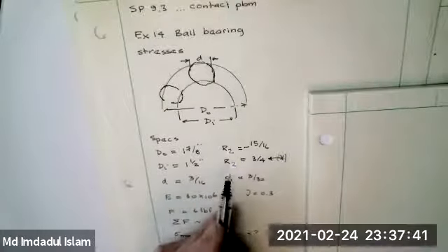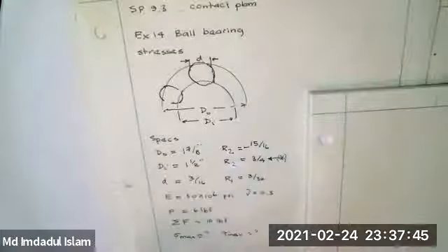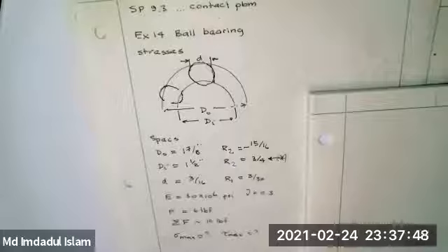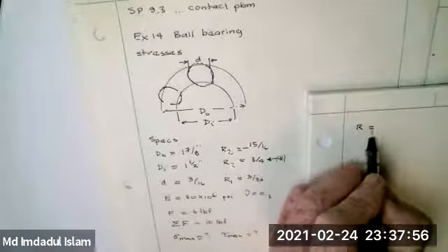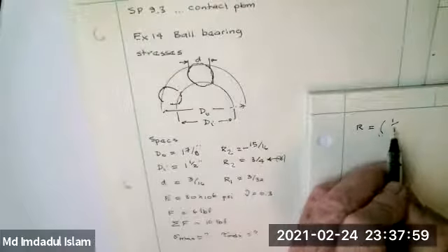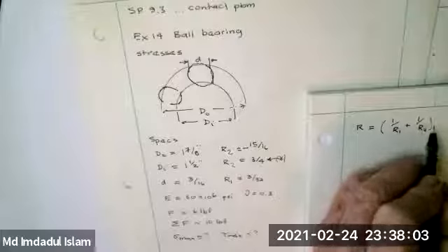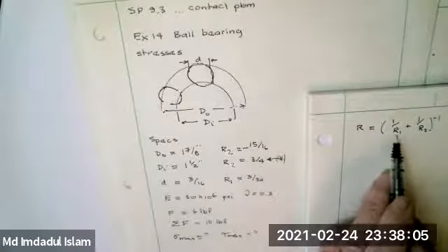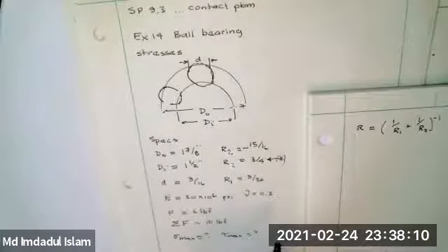As I said, the max is at the inner race, so we need to go and get R. It'll have the smaller R. Let me show you. When they're both positive, the sum will be bigger. So when I take the reciprocal, I get smaller, so I get a smaller contact radius. Contact radius is proportional to R.